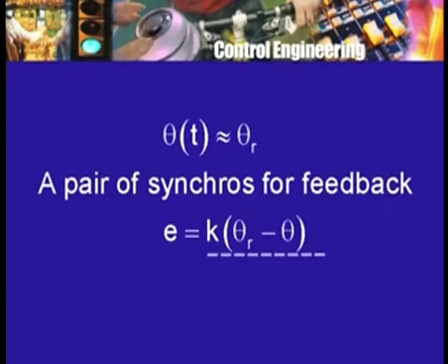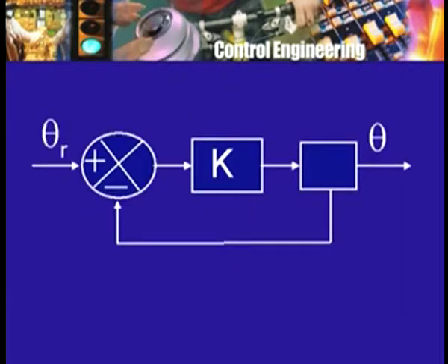So, in addition to this k theta term which is occurring here, I could also introduce the derivative of theta, or omega, as one more term in the feedback loop. So, here we can have proportional plus derivative feedback in quite a natural way, because the derivative of the quantity of interest, angular position, is a physical quantity which is measurable quite easily, speed, by means of a tachogenerator.